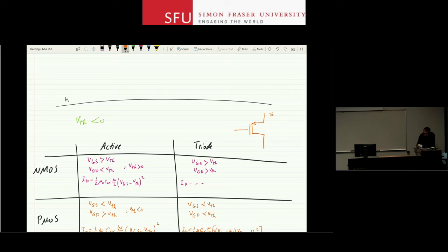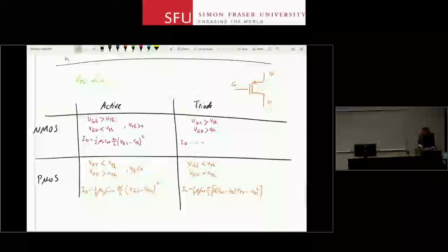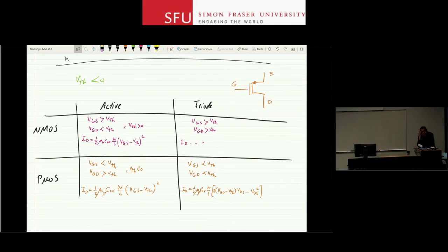So source at the top, drain at the bottom, and gate here. Similar to a PNP device. You know, we put the emitter at the top because of how we usually connect the voltages to these devices. In most cases, the drain voltage is less than the source voltage in a regular PMOS, right? So VDS is actually negative. So this is a negative number multiplied by each other. You get a positive number at the output. And then VDS squared obviously is positive as well.